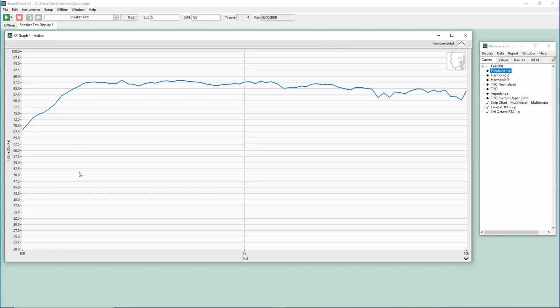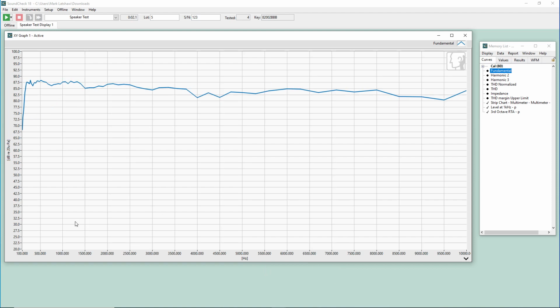The options on the x-axis are the exact same as the y-axis. We can enable or disable autoscale, set a format, change the precision, and then switch the mapping mode. Here is where changing the mapping mode to linear or switching the format to absolute time could be necessary.